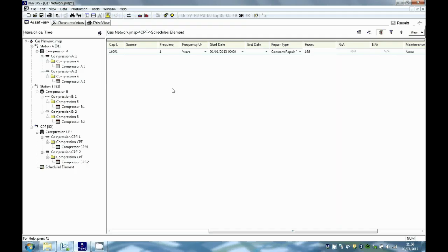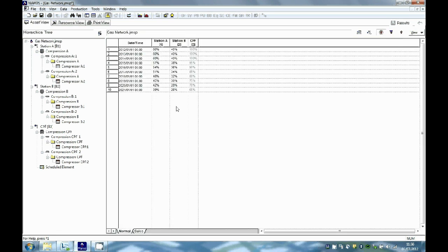When defining the demand profile, we know that there is an annual offtake of 65% of the design capacity for the first 6 months of the year, and for the last 6 months of the year, an offtake of 50% of the design capacity. So to define the demand profile, open the flow table, so go to view, select flow table, and select the option sales.